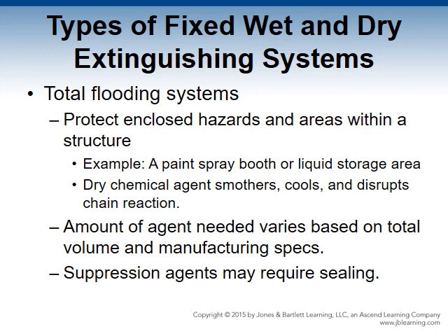The amount of agent and the number of nozzles needed depends on the area's total volume and the extinguishing system and manufacturer specifications and approvals. For some agents, especially gas-based, suppression requires sealing or minimally opening the protected area. Protection should include automatic shut-off of openings and stop forced air ventilation systems before or during discharge. This ensures the concentration of the agent does not decrease and result in inadequate suppression. If openings cannot be closed, another agent must be added to the design.